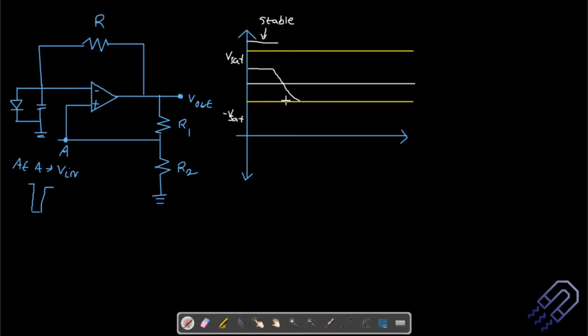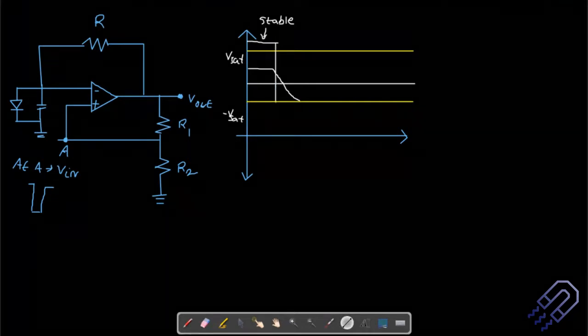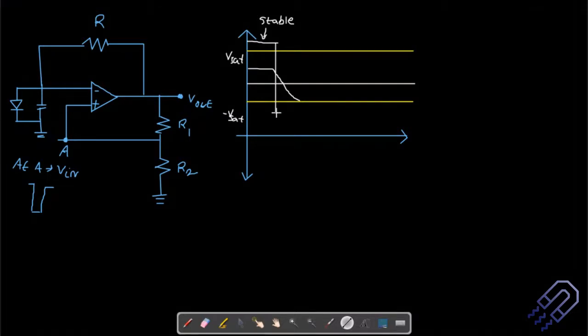As soon as we apply a trigger, the capacitor starts discharging, and this trigger results in leaving the stable state. So it will go into the unstable state, to the minus V saturation. Then it will stay there for some time depending on the value of R and C, and then it will again go to the stable state. If we apply a trigger, only then this happens, else it does not happen. So this is something which you have to understand.